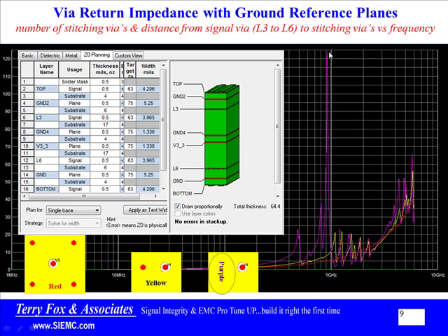Now if you'll notice at about, I don't know, 920 megahertz or something, that via has an impedance pole or impedance spike that looks like almost 120 ohms. So this is a very significant impedance spike. Now why is that important? Well, it's important because these traces, when we're trying to build controlled impedance stuff, typically look like 45, 50, 60, 65 ohms, something like that. So that would be a normal thing. So if you could imagine putting a resistor in line that looks like 120 ohms, do you think that would have an effect on the circuit?